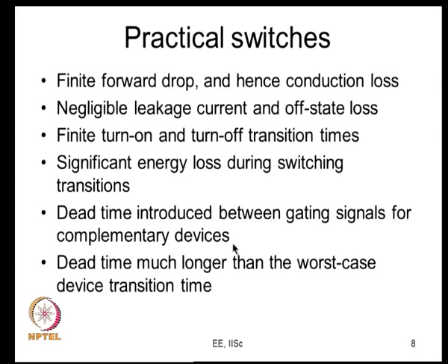Now, how short is short, or how long is long? This has got to be much longer than the worst case device transition time. The device takes a certain amount of time to switch on or switch off, and these transition times depend on the operating condition, so they change. There are conditions where the device transition times are longer, so you consider the worst case device transition time and choose your dead time to be much longer than that.